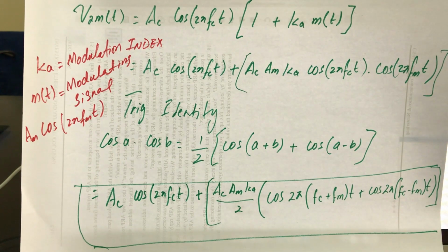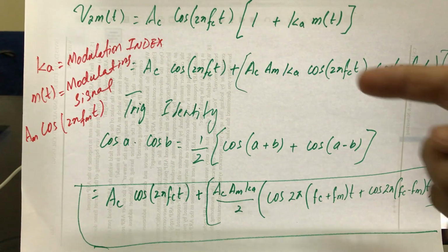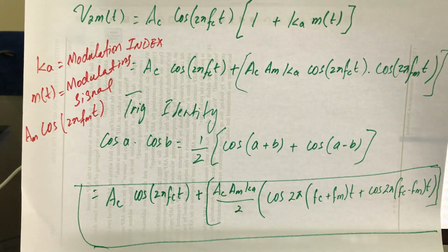This video is about amplitude modulation, how I can make an amplitude modulated transmitter using GnuRadio. So I'm just going to simply go over some math. The reason I wanted to show you the maths behind it is that I want to take this mathematical equation and transform it as is using GnuRadio. What GnuRadio allows me to do is look at my equation and transfer that equation as is in the form of a flow graph.